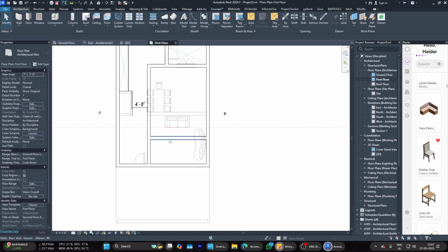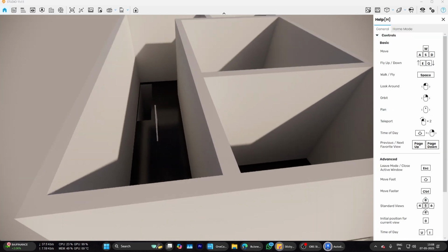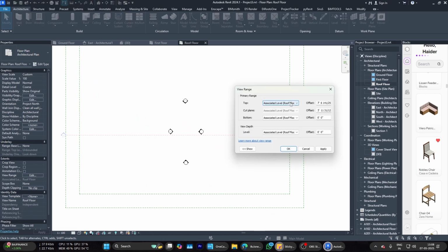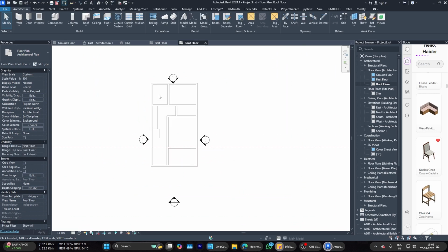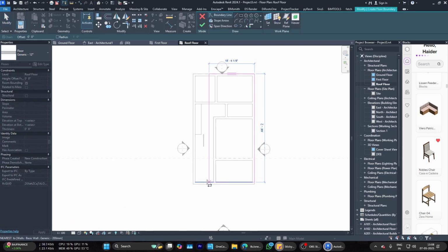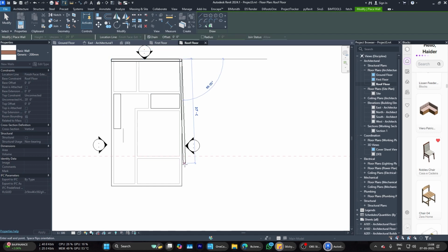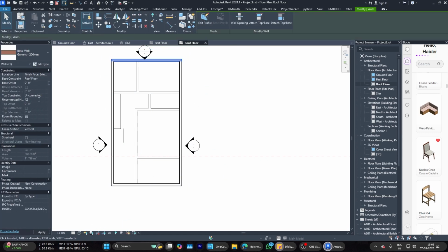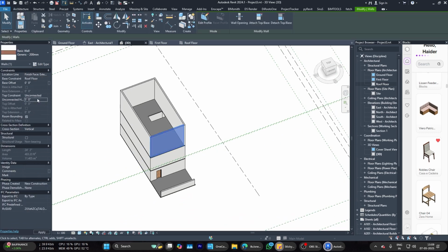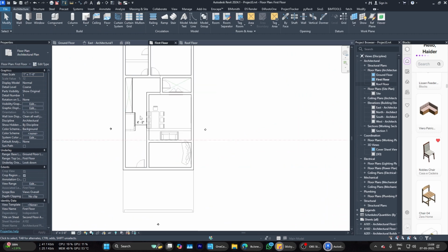Here, the first area space we will use for the terrace and the balcony, and another one is the bedroom. There are two bedrooms. You can place those two bedrooms. And here you can see, this is the roof floor. I made the direct slab. Okay, the parapet wall with a height of 42 inches. It means 3.5 feet.